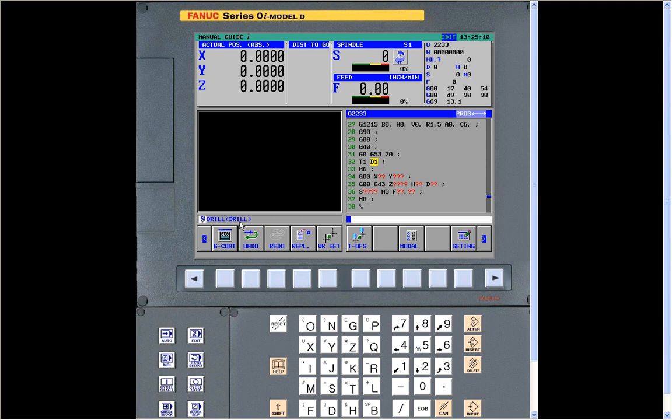See, as soon as we do that, it comes up, okay, it's a drill. That's what we want. Our position move is 0 and Alter in X and Y. Our positioning move in Z is 1 inch. And then H1 is our tool length, and D1. Now this tool work, again, we're going to run this at 3,500. We've got a good solid carbide drill. And our feed rate is 10.